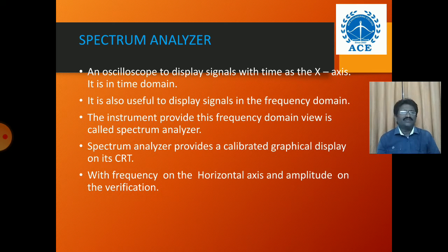Next, to measure such distortions, we have three methods. The first one is the resistance method, the second one is the Wien-Bridge method, and the last one is the T-bridge network method. Here also you have to adjust the fundamental frequency with the help of tuned circuits.